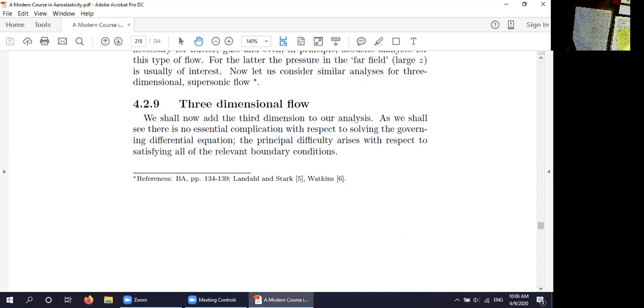And one reason I like their solutions is they plotted K as well as the lift versus time. And K has an interesting structure, as you see from those official solutions. It starts off at 0 and goes back to 0 in finite time, reflecting the fact that there's a finite memory in the supersonic flow, which is actually true in both two-dimensional and three-dimensional supersonic flow, because the memory only goes back as far as it takes a fluid disturbance to go from the leading edge to the trailing edge,